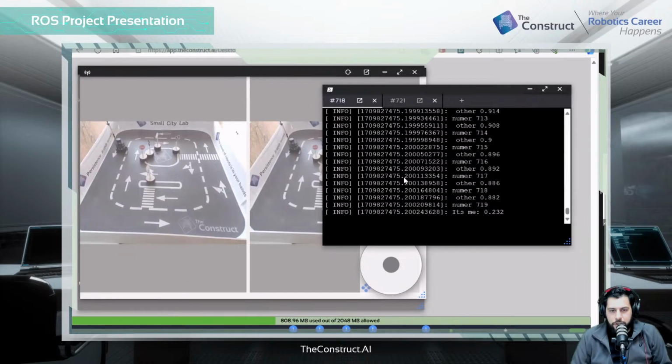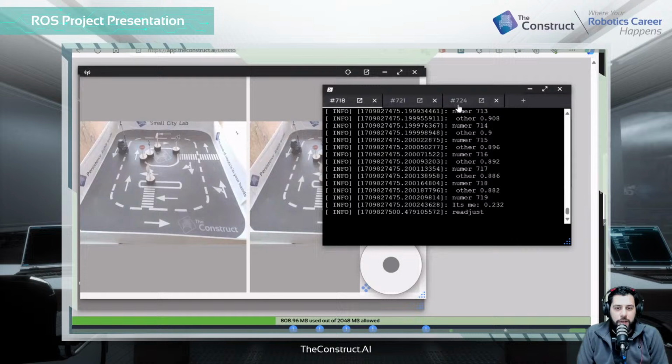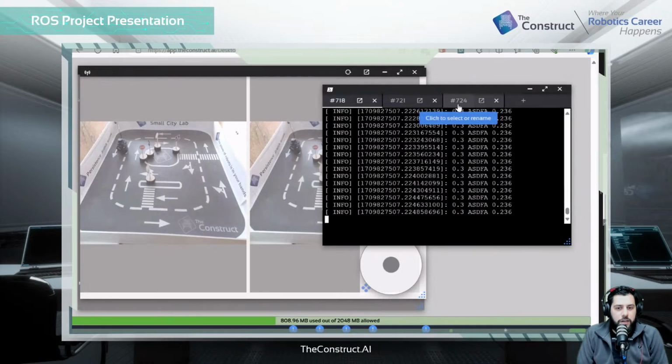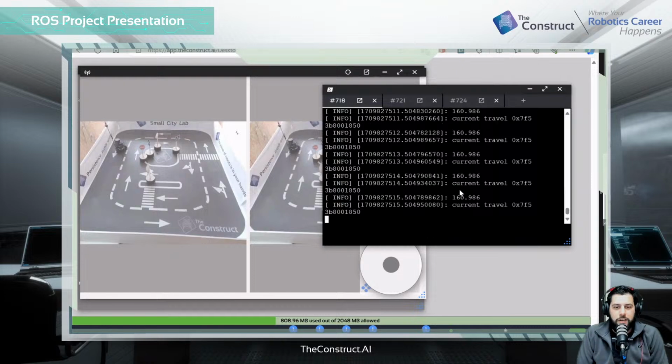Okay, so what it's doing right now is finding the wall. What I did is it's gonna rotate at that speed until the front laser measures the same distance as the smallest wall distance. Better slow than quick and for it to miss the spot. Okay, it was supposed to find it there. Let's give it one more. Okay, it did find it, and since we were at the right distance, it didn't readjust the distance.